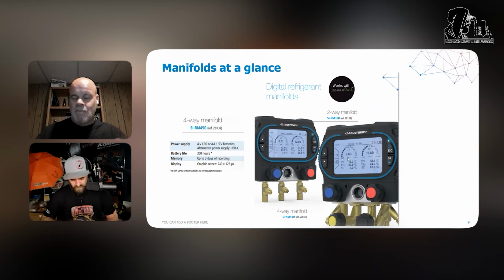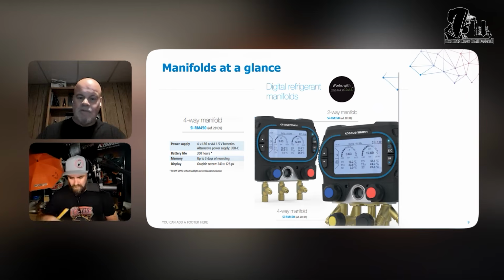You can hit it with positive pressure of up to like 380 psi, which a lot of them only go to like 140. If it's going to get banged with positive pressure, it can really screw things up. So for the micron gauge, we have it covered there. If we read between the lines, we know how someone's going to use it. We also know the pitfalls of what can happen while being in use. So we have that downside protection to protect the end user in case something gets a little hairy or gets out of line.